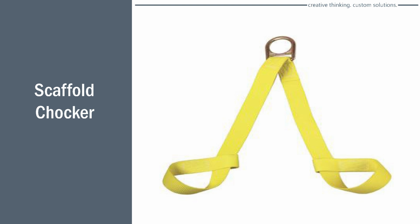Here's another device people use as a scaffold choker, but you would use this on the back side of the scaffold compared to what side you're working on. You don't want to tie off on the same side of the scaffold as you are working. If you tie off behind you, you have less chance of falling off of that scaffold if you lean over the handrail.